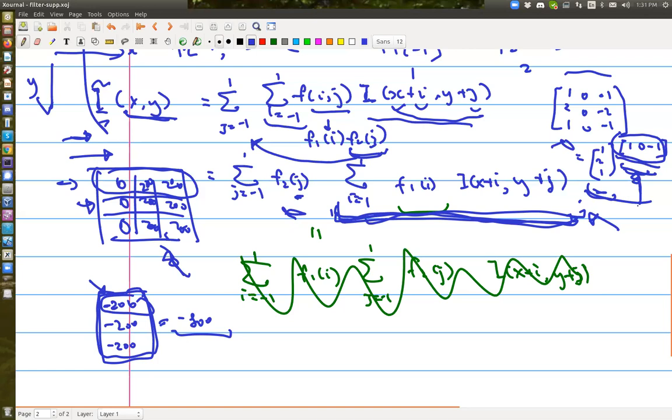So that signal will not be filtered horizontally by this high pass filter. And along the vertical direction, the vertical edge is a low pass signal, which will not be filtered by the low pass along this vertical direction. Therefore, I get this signal passing through, and therefore I can detect the edge.